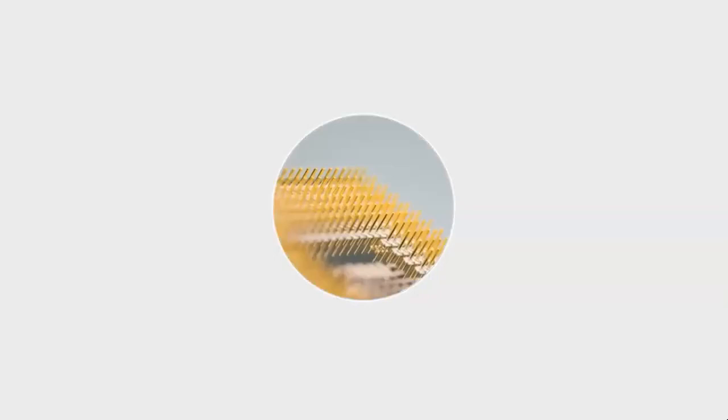Sir, can't we adjust the mesh thickness? Abdul Munir, here there is no need to adjust mesh thickness. The mesh thickness doesn't come into play here, because first we used Octree. Next we used Delaunay. Automatically it will optimize things, so that's not a big issue. So any other doubts, guys? Further, we can refine a mesh to around 20 lakhs, but that is not a requirement here.